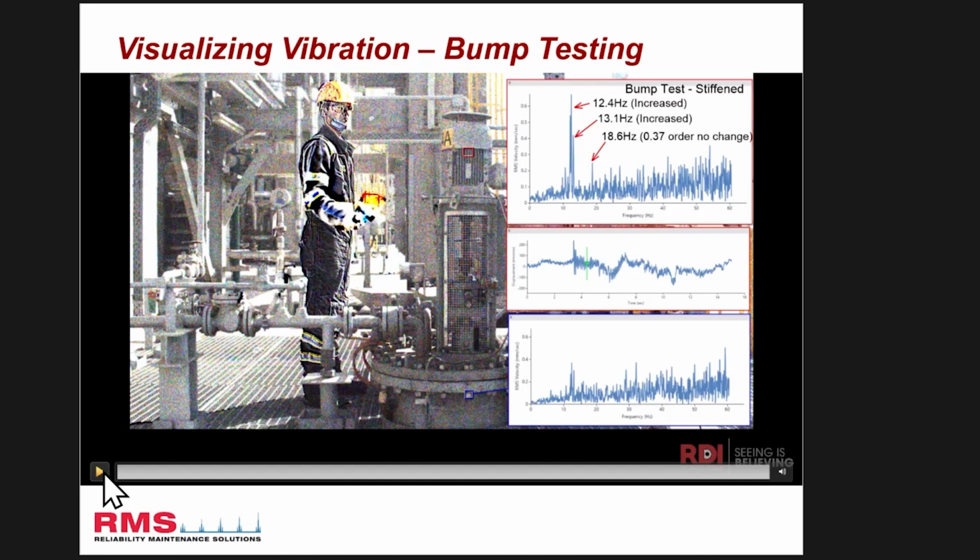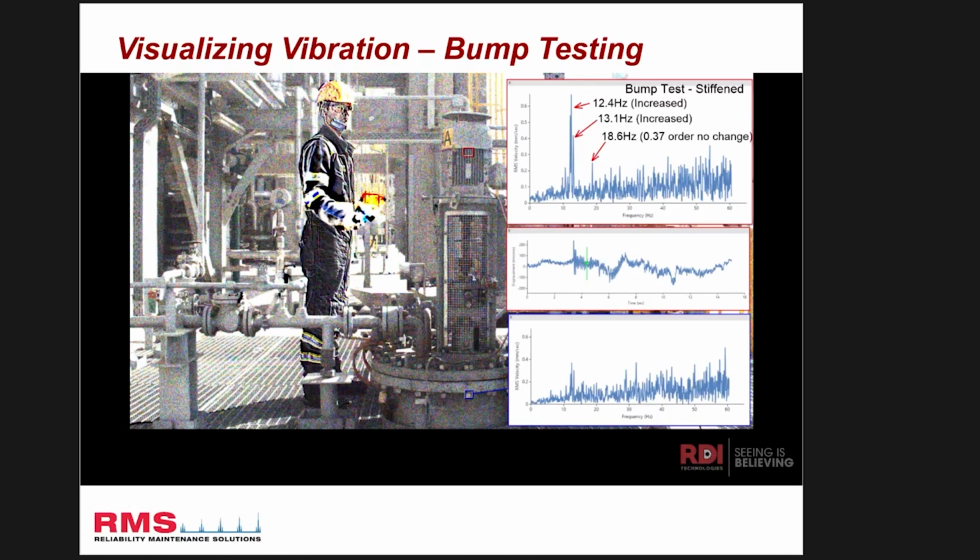Normally we do an impact test with a modal hammer and accelerometers maybe, but in this situation we can apply the same procedure and get similar results. So the camera is quite good for doing things like that as well. In a situation like this, you really don't have to worry about mass loading with an accelerometer. Exactly, because it's non-contact. But if you're using an accelerometer, it's so light compared to the rest of the structure, you don't have to worry about the mass loading of it. But in the case of the Formula One car, that would have been a problem.